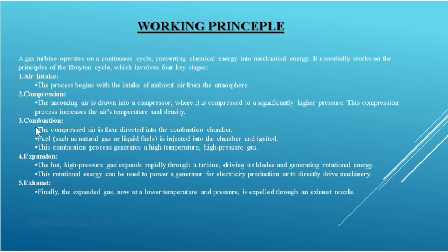Then the combustion chamber. The compressed air, now at high pressure, passes directly into the combustion chamber. Fuel such as natural gas or liquid fuel is injected into the chamber and burned. This combustion process generates high temperature and high pressure gases.